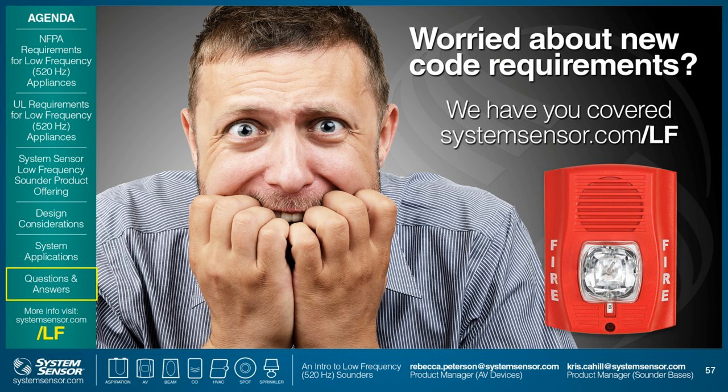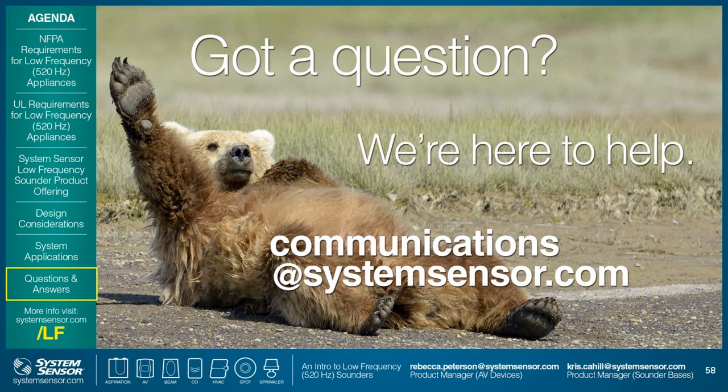As we have mentioned in this webinar, the reason is because we're using a speaker, and also because of the square wave format profile. It's so much energy that you need to generate to meet that format that the devices just draw much more current. So when you're designing your NAC line, if you're used to using a horn only or a mini horn, be aware that the current draws will be higher.